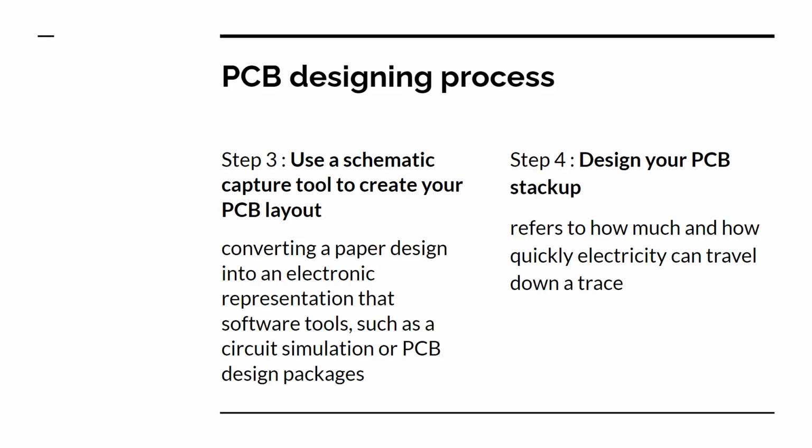Another area is to design your PCB stack up. This is not a required step, I would say. If you are doing simple PCBs, you don't have to do this, but what they're trying to say is it refers to how much and how quickly electricity can travel down the trace. So it's about proximity, and if you are doing PCBs with 2 layers or above, you are going to refer to this so much rather than if you are doing a single layer PCB. We will see that when we go into practicals.